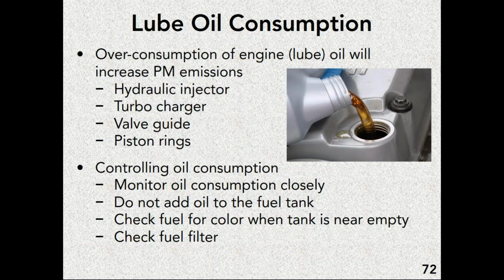So I mentioned oil sample because one of the biggest issues with filtration systems failing is engines that burn too much oil. This could be overconsumption of lube oil, hydraulic injector oil, turbocharger oil, valve guides are worn out, piston rings are worn out. All these things can cause too much oil consumption.